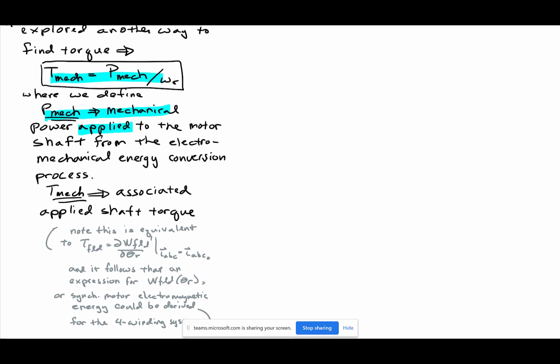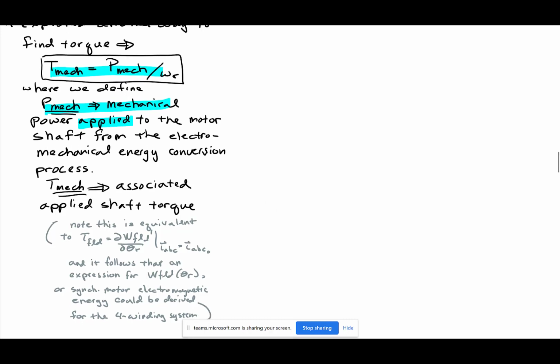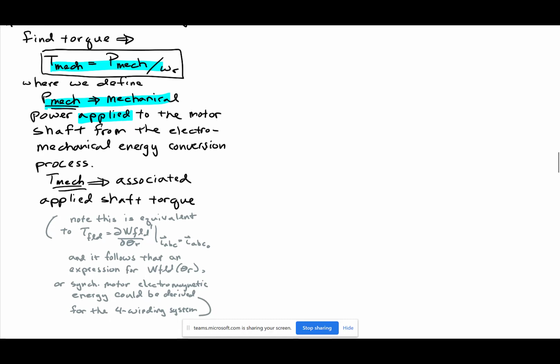That's really my definition. The book is not super clear on this, but this is engineering practice: the shaft power. If you always assume that you're given a horsepower and it's shaft power, and that there's some mechanical efficiency, that gives you a little bit of margin in your design. And so it's always a good idea to make this assumption, even if it's not given, because practice isn't always consistent in the way people describe this.